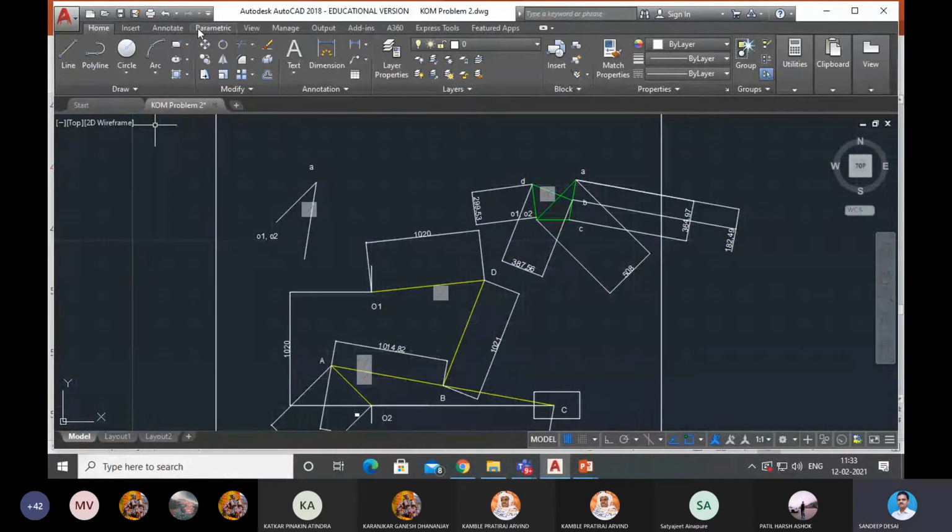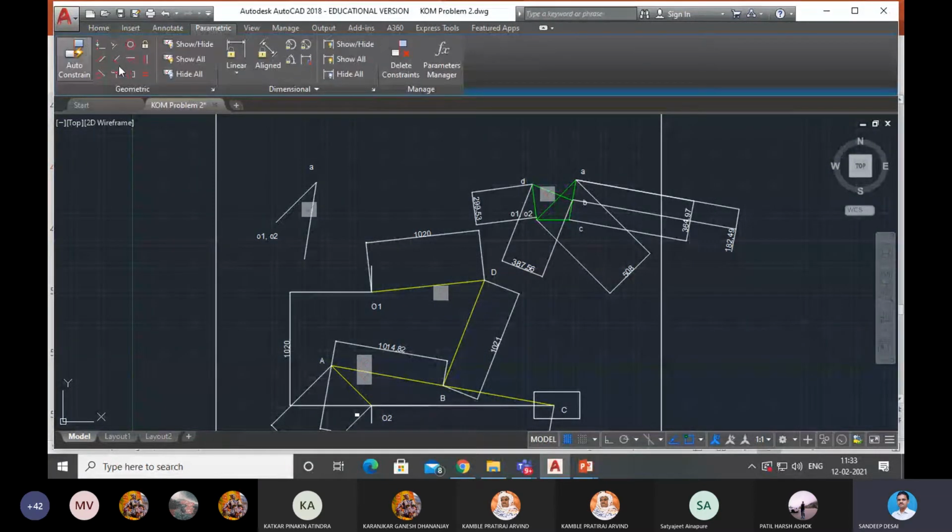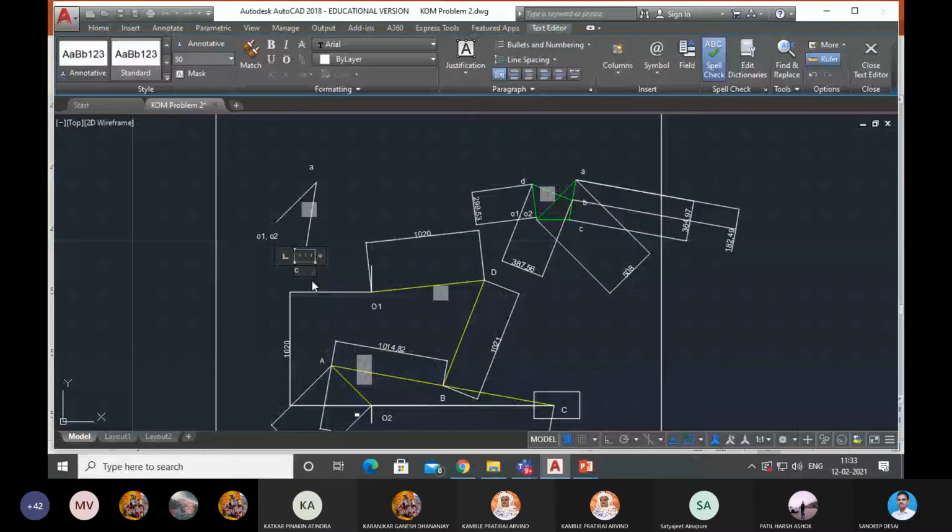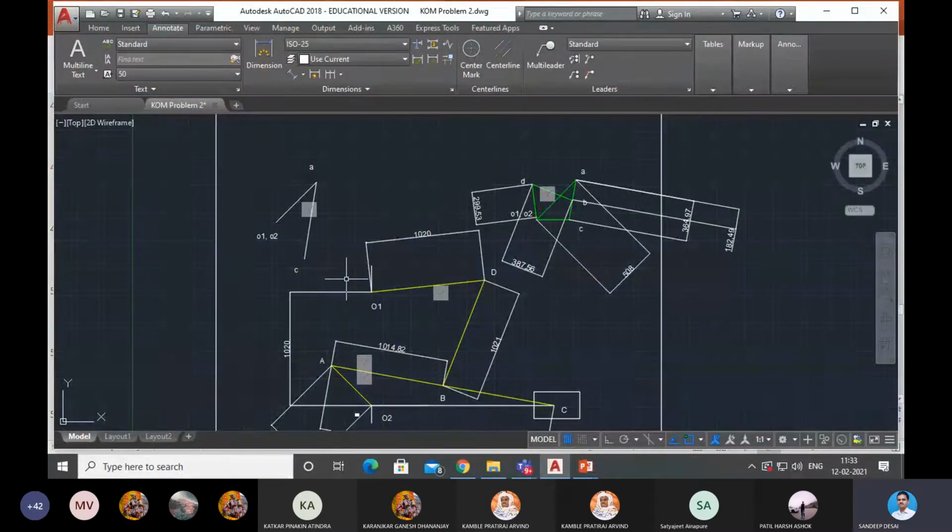I don't know where C is. Let me write here C. Please observe everything very carefully. Don't miss anything. C. I don't know the location of C. I don't know the magnitude of C. I have just approximately written point C here, but that is going to change later on. Then the velocity of slider C. The velocity of slider C is always perpendicular to OC.